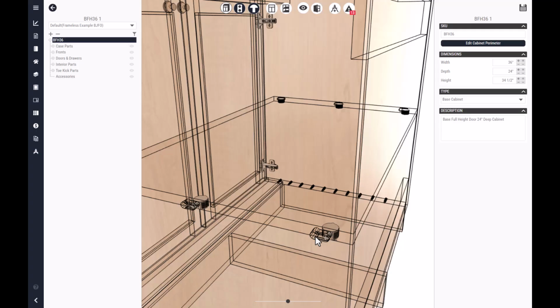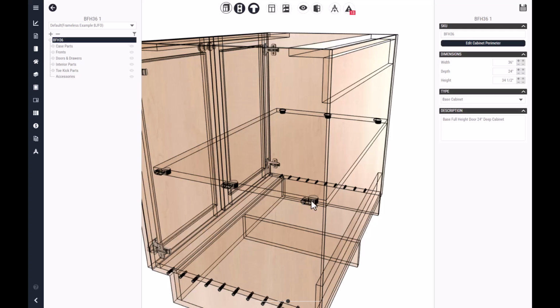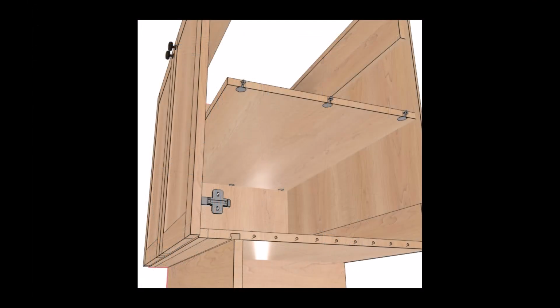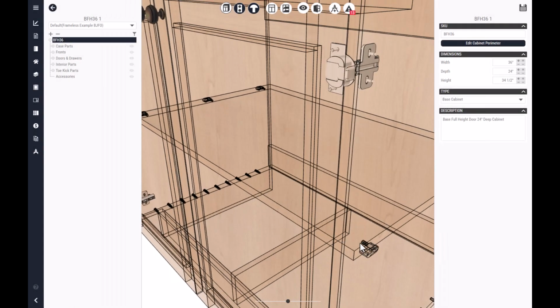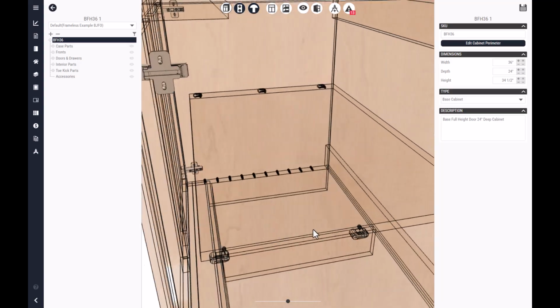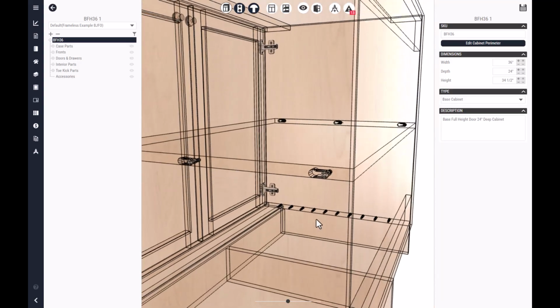Verify the center's arrangement, first or end position, spacing or quantity, last minimum distance when applicable, and parts gap. For Peanut 1, verify the routed slot and both connector recess holes on the panel face, and confirm that no edge bored hole is expected. For Peanut 2 or Peanut 3, verify the face routed slot and the matching 6mm edge bored hole, then identify which machine or production step will create each operation.